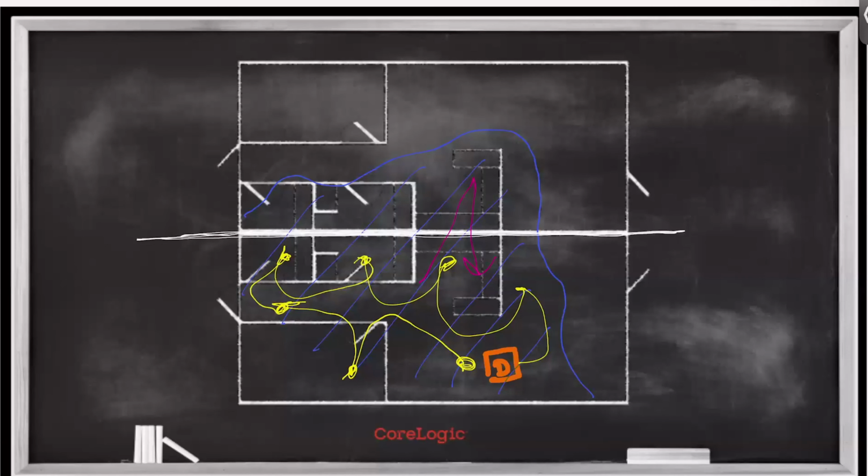Most cases, that's not going to be what we have. So we'll end up with drying chamber 1 as unit 1 and drying chamber 2 as unit 2. And then again, to validate that my humidity control is effective, and this is the key and something I really want to drive home, hopefully as a point of action or an actionable item to deploy in the field, take a temperature and humidity reading at one location in your chamber and at the opposite end of your chamber. You have humidity control if both of these readings are the same.